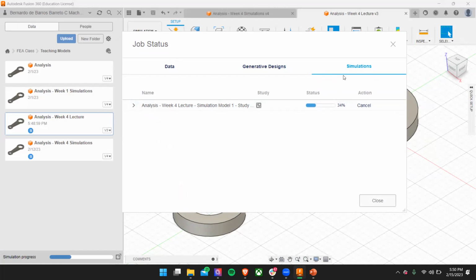What is the minimum member size? So the minimum member size creates a lower boundary. When you shape optimize, I'll show you what it looks like. There you go, so this is what happens. The system is telling you, okay, you can basically get rid of all this, right? The minimum member size tells the system, I don't want it to go below this certain width or height. It just gives a lower boundary measure basically. And yes, this is exactly what I wanted to go through.